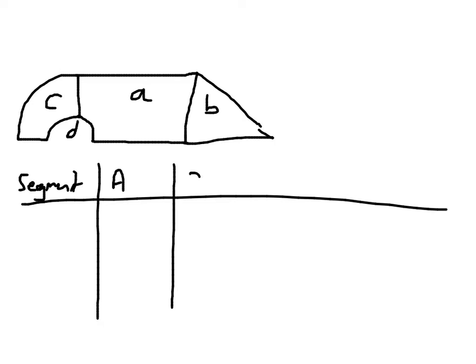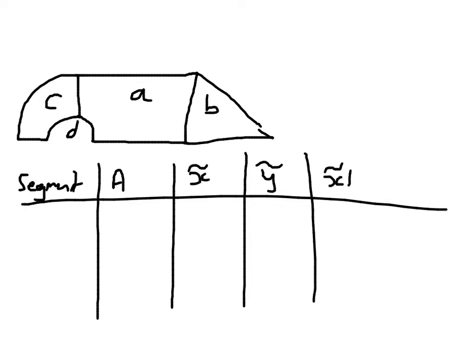and we're going to want to find its X position, its own individual centre of mass, and its Y position. And I've said centre of mass, I do apologise, I meant centroid, because that's what's asked for. And then, similar to the previous exercises, we've been finding X tilde A and Y tilde A. So we're going to find the central position of each of these shapes, and then we're going to work out how they all relate together.